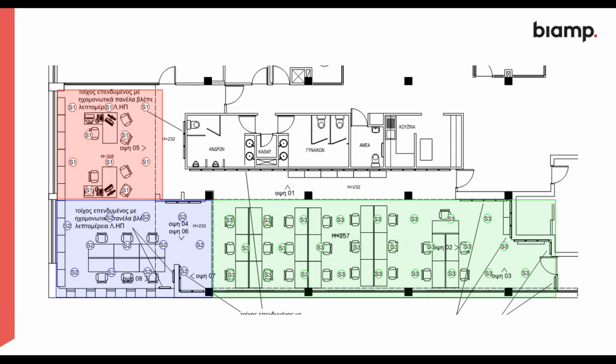Can I get a wall mount case? Oh, yeah, this is a key one. Somebody's asked whether we can put emitters on the wall or is it only ceiling mounted. If we go back to the 4 key elements where we want uniformity, when we mount emitters on the walls, it is very, very difficult, if not impossible, to get uniformity. So we should always put the emitters hanging down from the ceiling or on the ceiling to get the uniformity.